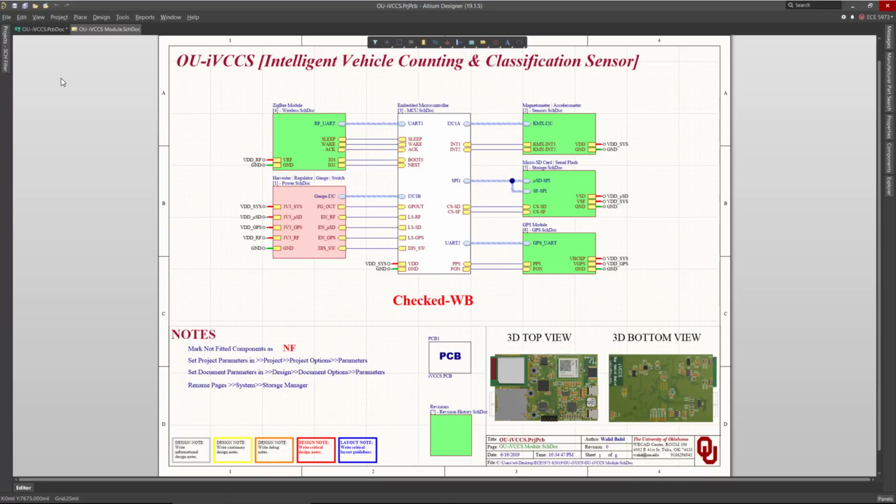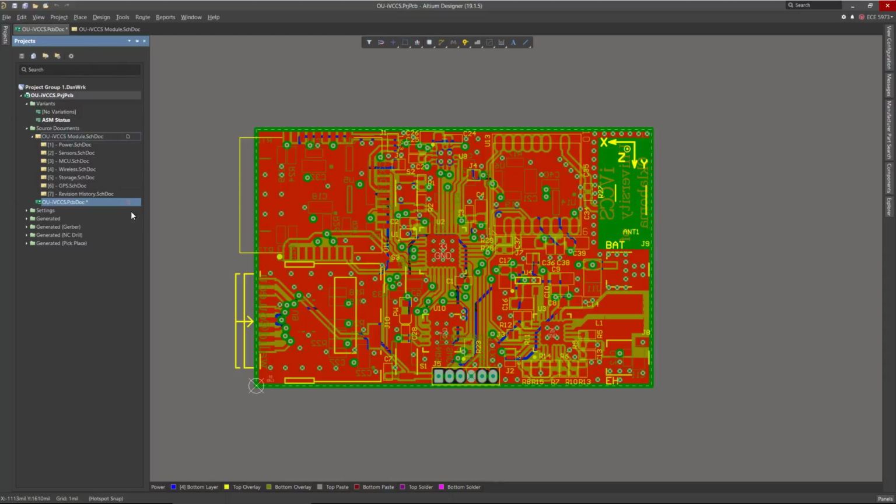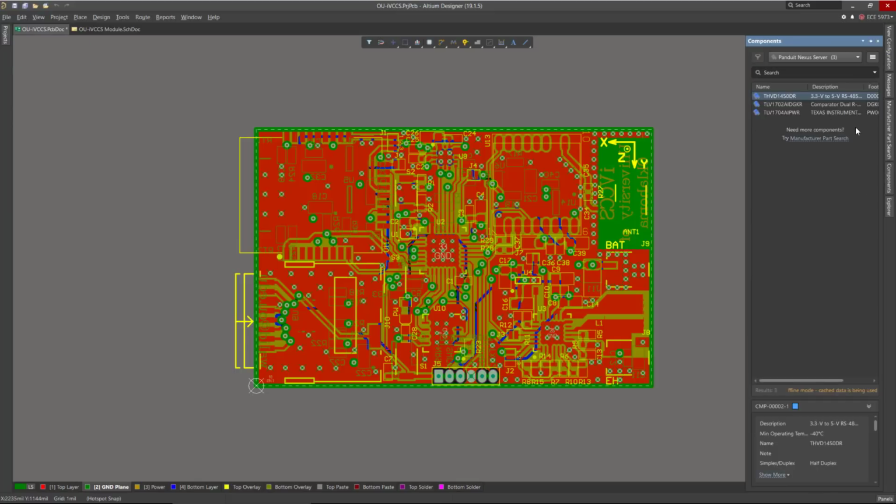When Altium Designer is first started, a number of panels will already be open, such as the project panel on the left side, or for instance the component panel on the right side, and this will be docked, as you can see in here. Of course, you can change that. Once you open or close specific panels, even if you close Altium Designer and open it again, it will restore the last configuration you made to these panels.